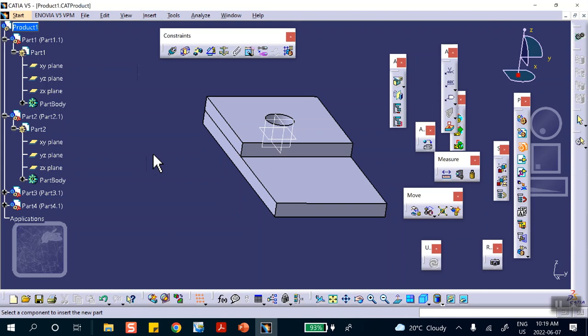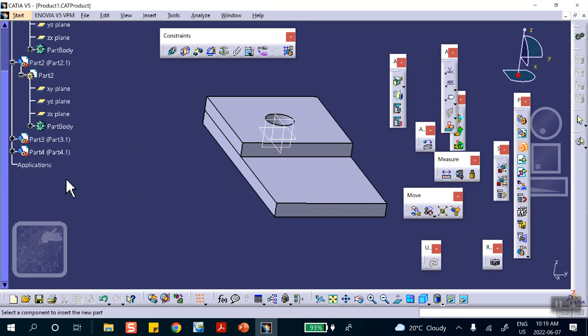In my case, I have a single product, but a product may be made of several different products, each one consisting of several parts. That's why it's asking where you want to put it. Maybe you don't want it in the top-level assembly. Maybe you want it in the sub-assembly, okay? But that is not the case here, so let me undo this, or delete it.